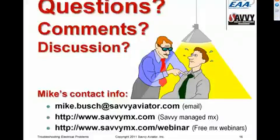Some aircraft have what's called an essentials bus. That's typically aircraft that have dual electrical systems, a primary system and a backup system, let's say like a Cirrus, where if the main charging system fails, there's a backup alternator and a backup battery that supply power to what's called an essentials bus, to which is connected just enough stuff to keep you flying.